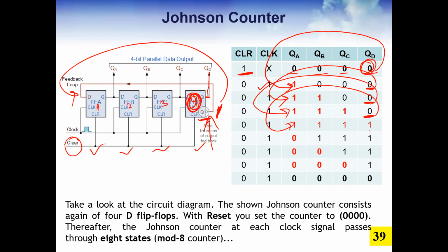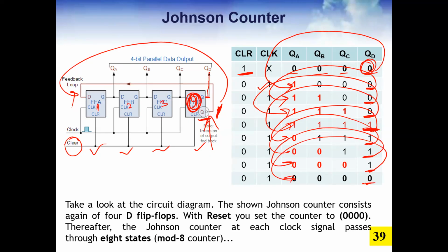So now this time it becomes 1. When it becomes 1, the complemented value will be 0. So 0 starts rotating. Still 1, 0 starts rotating. Still 1, 0 starts rotating. Still 1, 0 starts rotating. Now it becomes 0. So what happened? It goes back to the beginning again. So this is how a Johnson counter basically works.